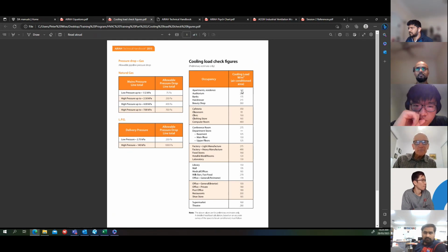So straight away, before you start doing your heat loads, you can get an estimate of what the load on the building is going to be, because this might help with your spatial allowances for condensers, how big the fan coil units are going to be, etc., etc.